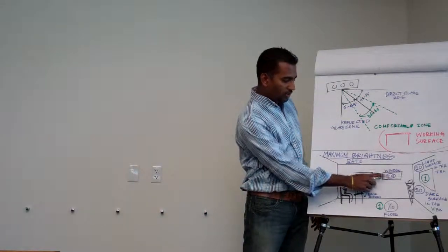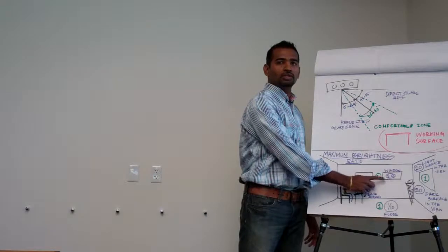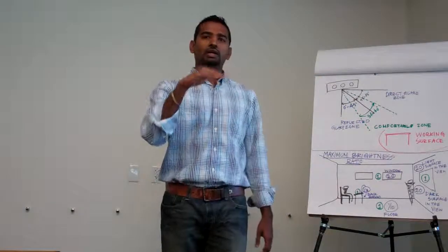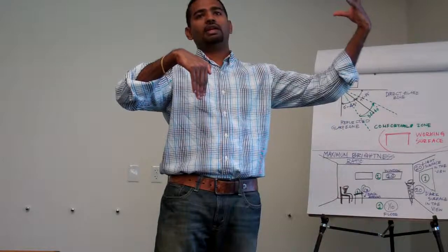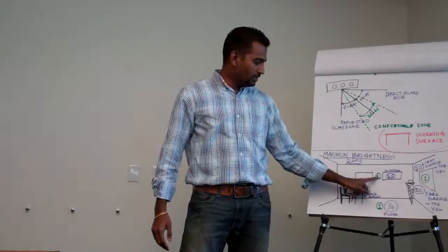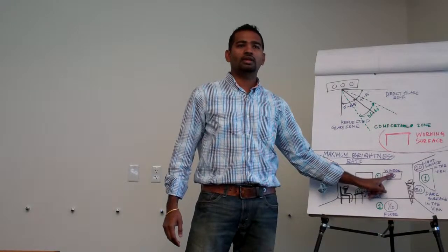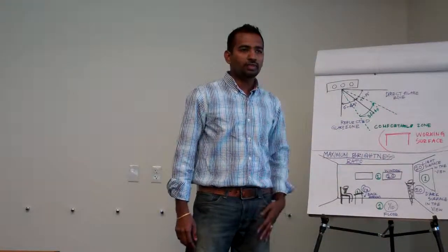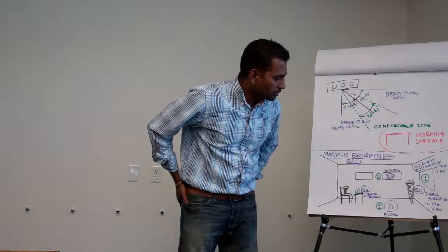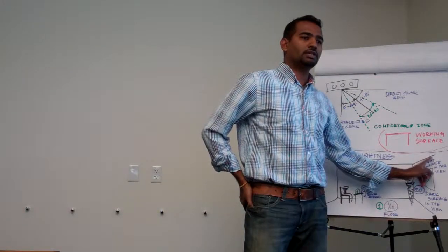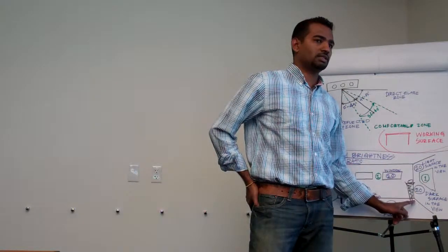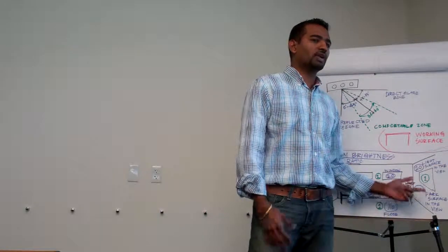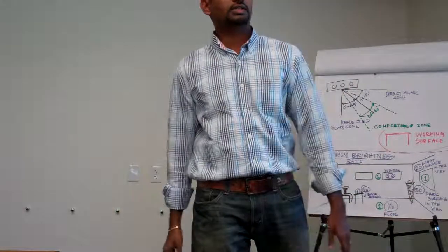Likewise, between a window and this surface, the maximum you want to have is 1 to 20. So that's why putting a shade in front of our window helps a lot. Because if you don't do that, it's direct sun hitting directly at the window, so the ratio between this surface and that surface is more than 1 to 20. Then it will be difficult for people in that environment. Why is 1 to 20 with the dark surface allowable? That's because of the reflection nature of that surface. Dark surfaces typically reflect less, if you don't have a dark shiny surface. Since it reflects less, you're allowed to put more light on it. Oh, okay.